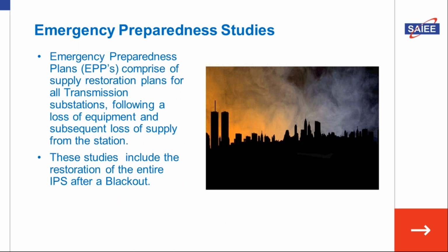And the other studies that we do, we actually help with the emergency preparedness studies. And here we look at the restoration plans for the transmission substation following the loss of equipment and subsequent loss of supply from a station.